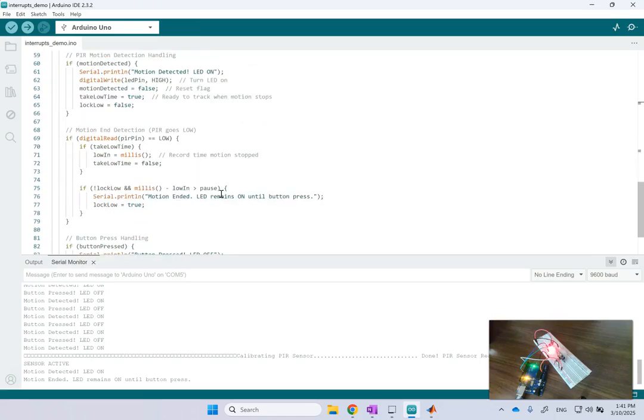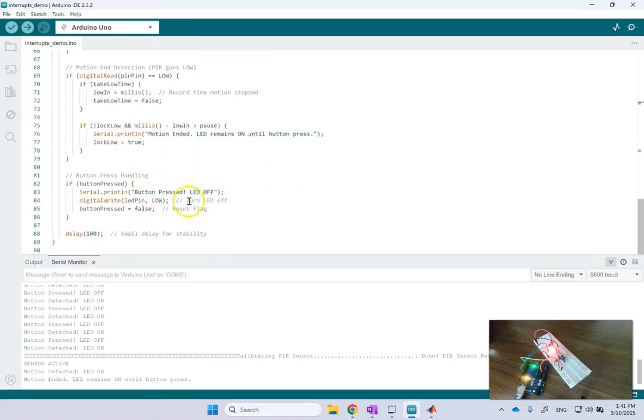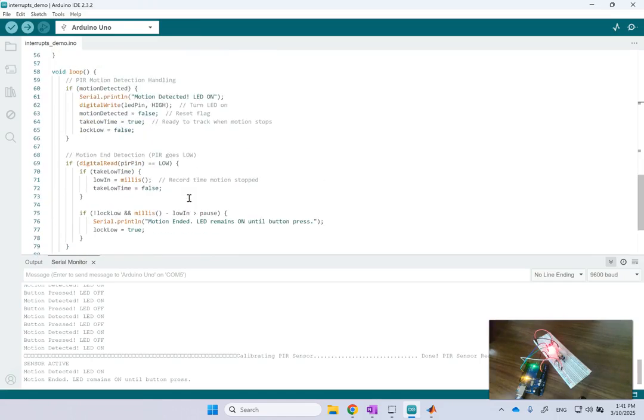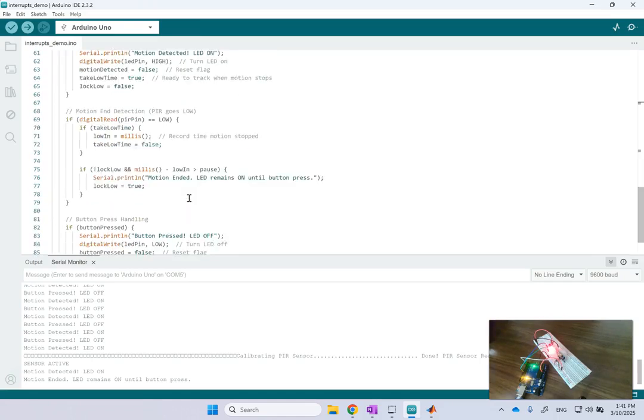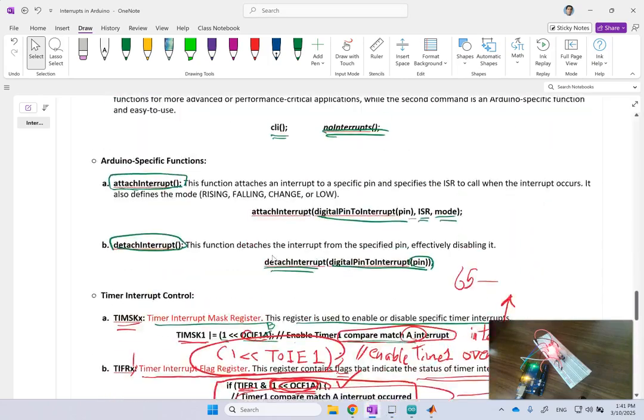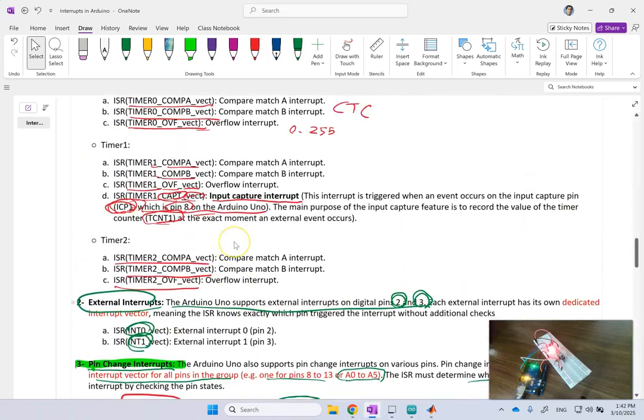And I did not use any other interrupt, as you can see, but if I wanted to, I can add a timer here, right? Well, kind of, I have a timer here, but without any interrupt. Because when I use function millis, millis is using timer number 0. So I am using a timer, but I'm not using the interrupt version of timer 0. So if you want, you can change this millis part and change it to something that is using one of these interrupts of timer 0.